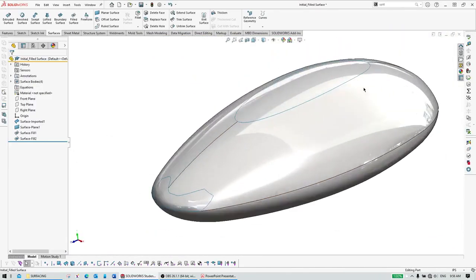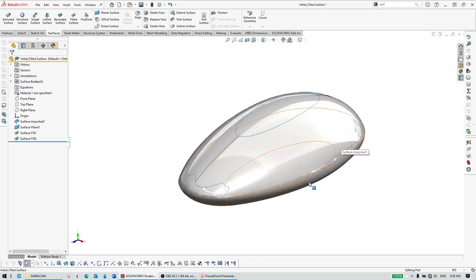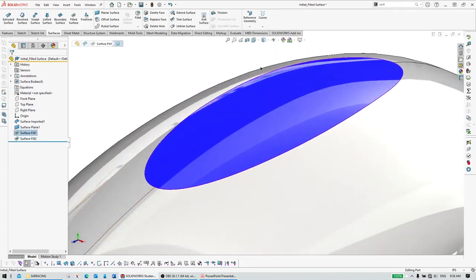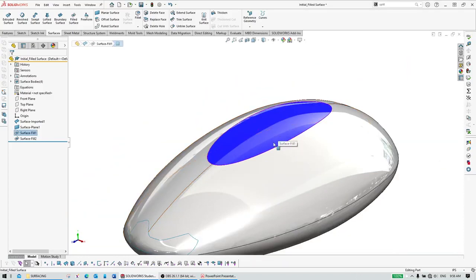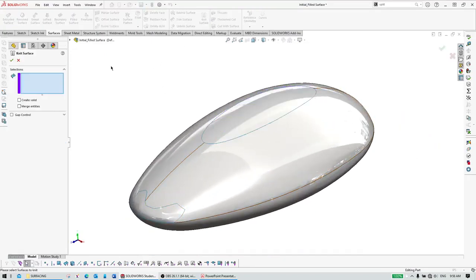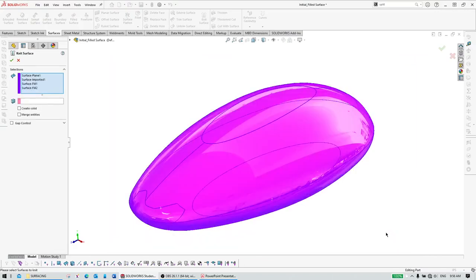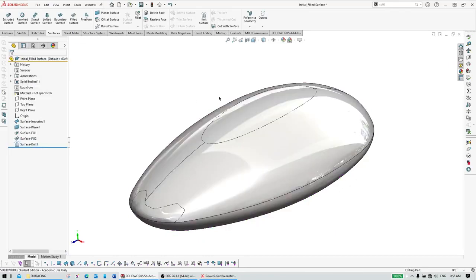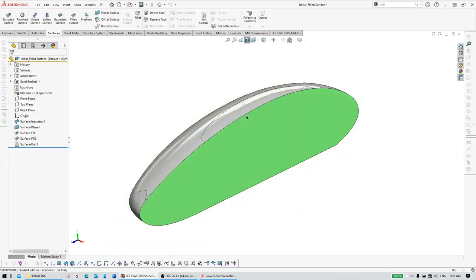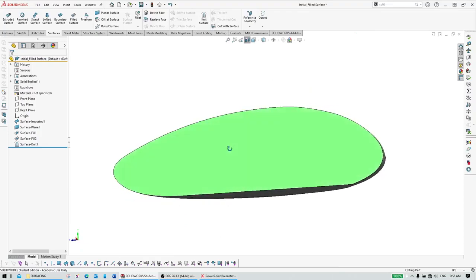As you see, this is really easy. Also, you might need to delete the surface and offset the surface up and down to create a new geometry. You can see these options as well, but first let's try to knit all these surfaces together. I'll show that option as well. Let's click OK, and over here we have Create Solid. Since we need to create a full solid, let's click that. As you see, this is what we expect, right?